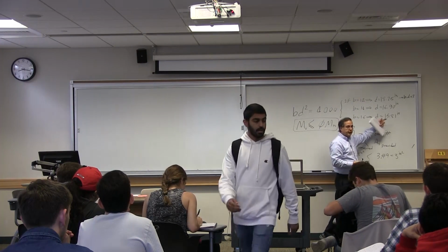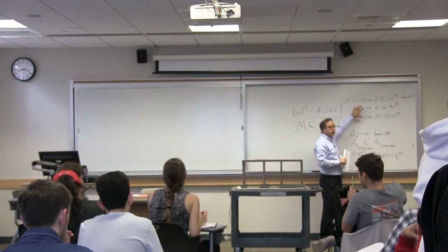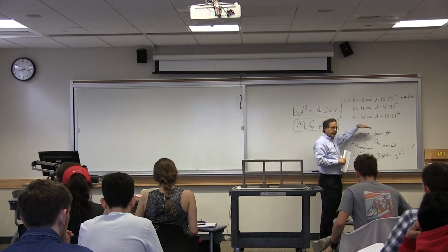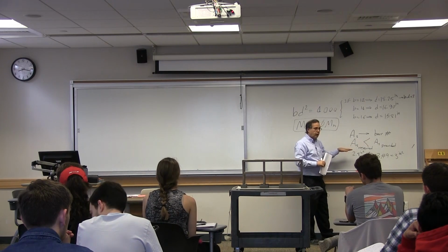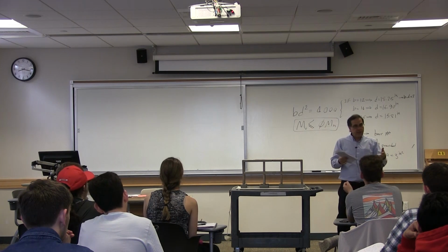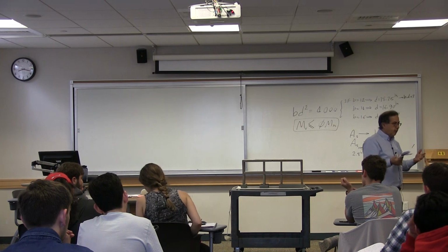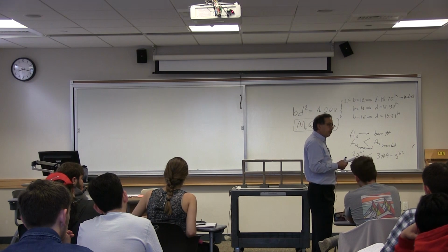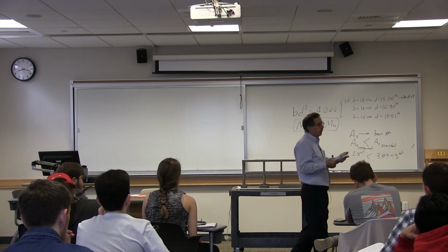You calculate everything, and at the end, when you calculate AS, in fact, there is another step. We round these things up. I'll talk about that today. Let's say you are not rounding them, you're just calculating your AS, and your AS provided is more. You don't need to go back. It's a good idea to check your Mn just for the sake of verification, but your phi Mn is going to be larger than Mu, and your design is complete. You do not need to redo anything.